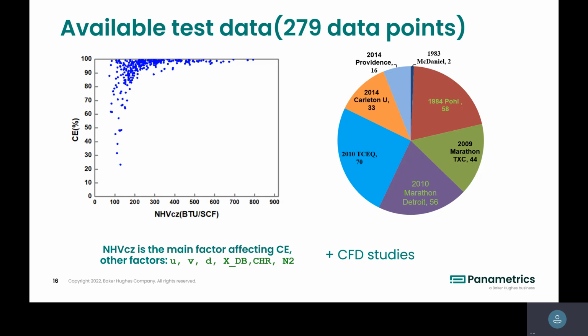Some other factors like wind, exit velocity, gas composition in terms of pi bond, the olefins or unsaturated hydrocarbons, carbon hydrogen ratio, and then also pipe diameter, hydrogen, for example, and non-combustibles, mostly nitrogen. All those can have an effect on your combustion efficiency. And of course, if you have assist gas, then assist gas is also part of combustion efficiency.